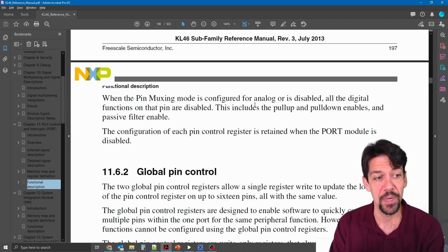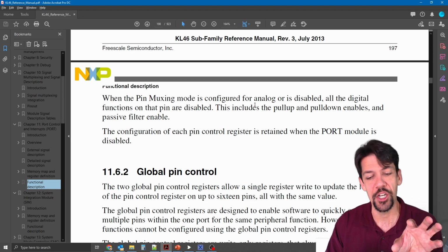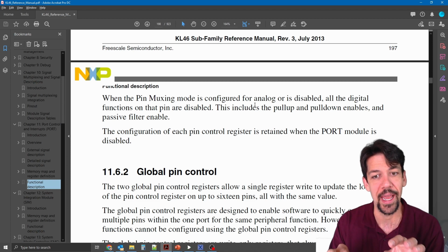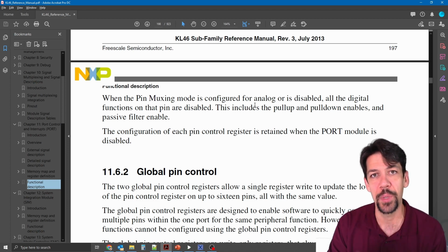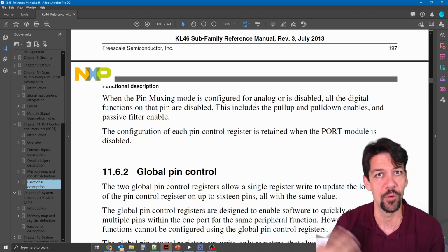And that means mapping the description of what to do to the registers that we need to set and what values to set them at by looking up these pin descriptions and memory maps, and then figuring out what the different fields do and writing code that sets the field to what we need it to be.